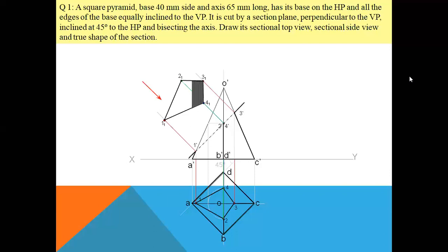Okay. So now the hatching is very important. As you can see, 45 degree. Now you will say, sir, how can this be 45 degree? Because this is the reference line and this seems to be 90 degree, isn't it? However, for this case, the section line will be the reference line. So if you consider the section line as the reference line, you will see that it is 45 degree to the